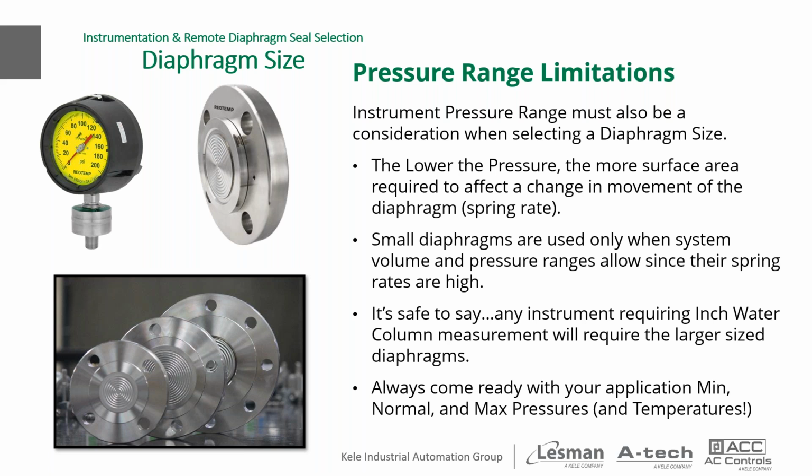You know, for example, if we tried to measure a span of 5 psi, and we used a 1.5-inch diameter diaphragm seal. Not a whole lot of science in this, but it's a small diaphragm seal, and that's a fairly low pressure. It's really just never going to work. So I don't know that I answered your question, but sluggish response, unbelievable response from your instrument, probably an indication that it may be.